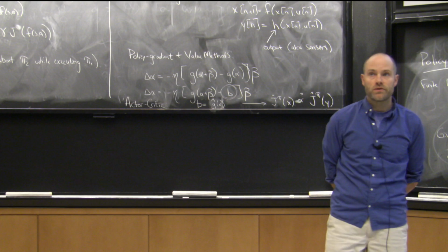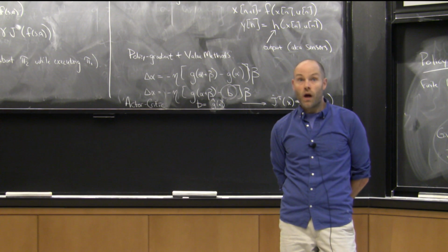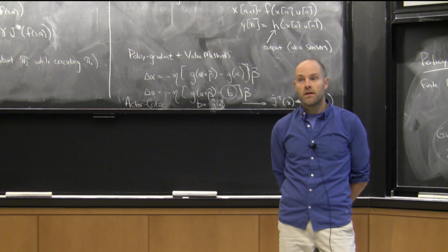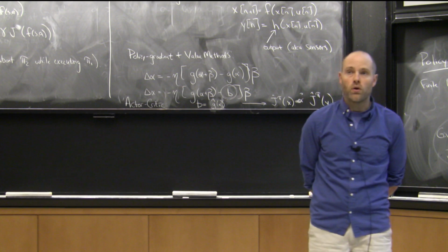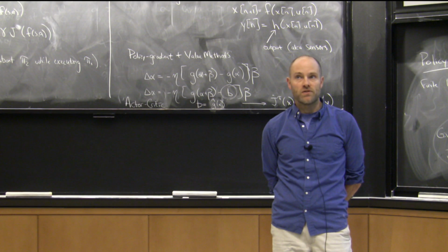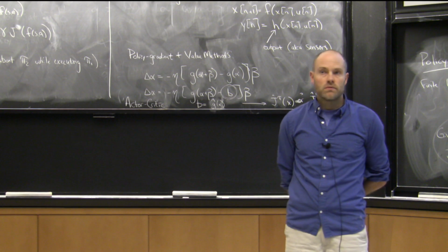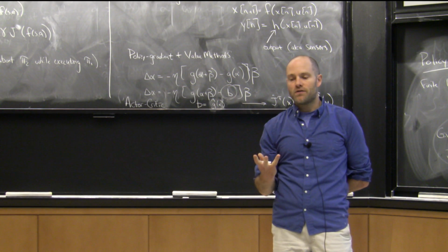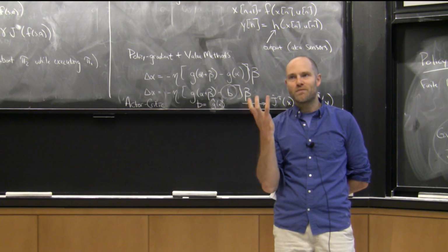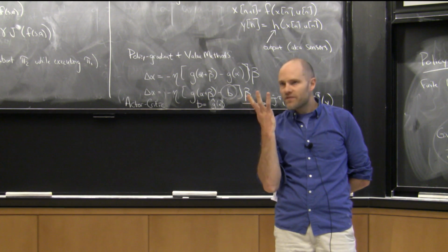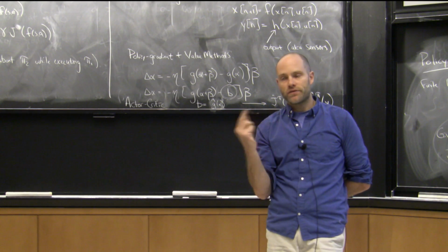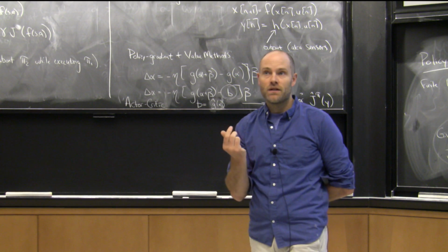But those are important big questions. AlphaGo, I think, was extremely robust, right? Human players could push it, and it was still robust. It's hard to know from the videos we've seen of reinforcement learning results on robots, but they don't seem to have the same levels of robustness yet. We're even trying to use deep networks to approximate the optimal cost-to-go that we can get from mixed integer optimization to run on Atlas, and it's very hard to come up with a network that you'd be willing to run on the robot, right? We're playing all kinds of games to try to use the two, and we have some work even on trying to do verification for deep neural networks because these are important questions.